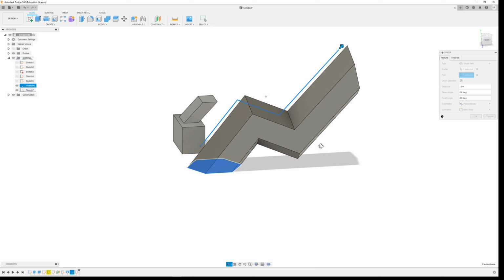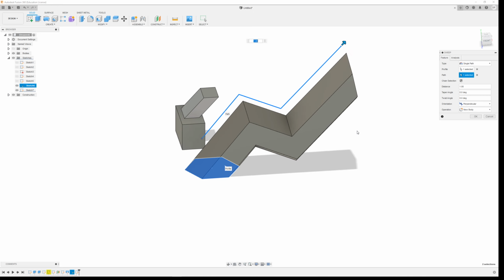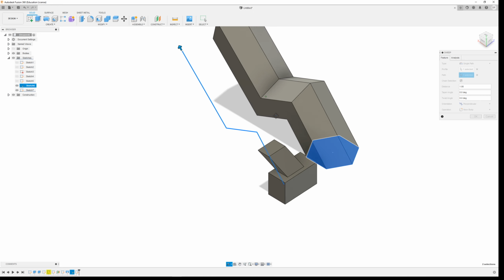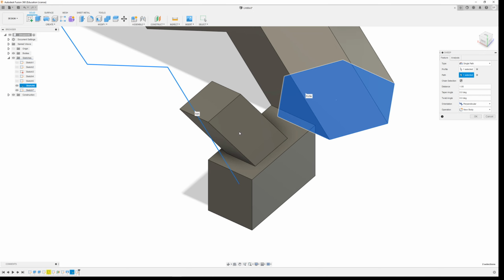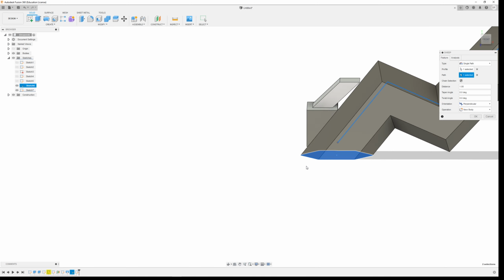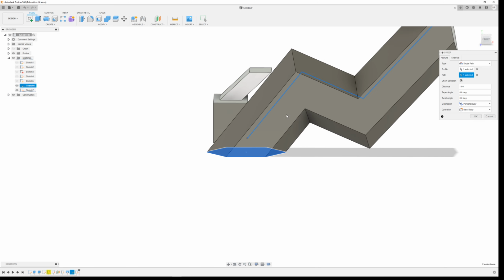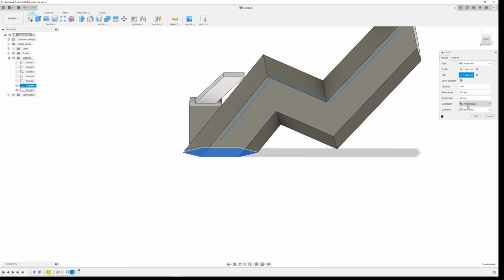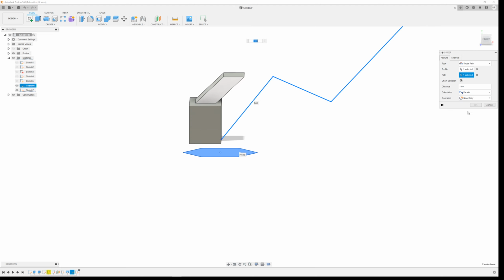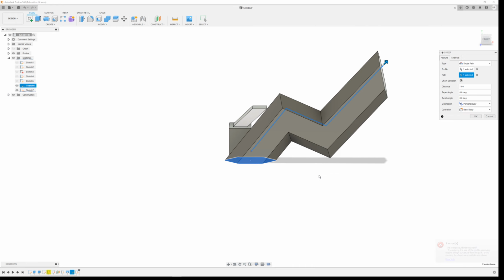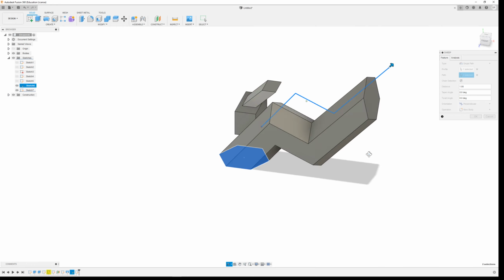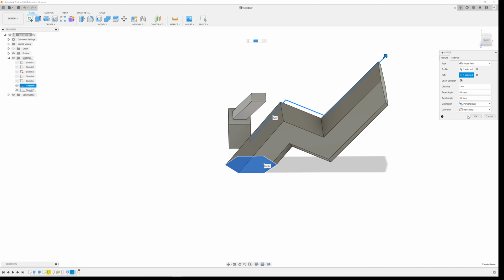And this works better if, with this particular loft, if you wanted to make it look like this hexagon shape, you'd have to do a different shape at every corner. But this one we can do all at once. We can do it parallel. Can we do it parallel? No. We can do it perpendicular. So it's always going to be at right angles to the line. Then we press OK.